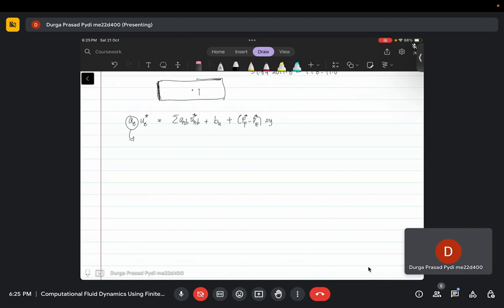This has a lot of terms in it. So let's say we are trying to expand a_nb. a_nb will have your F_e terms, a combination of F_e and D_e. It has both terms from F and D, and this F will in turn have your rho u delta y. So how do I get u? That is exactly your question. I'm talking about the left-hand side. This left-hand coefficient is something like your a_P term, essentially sigma a_nb, so if you know these terms, you will be able to calculate this.